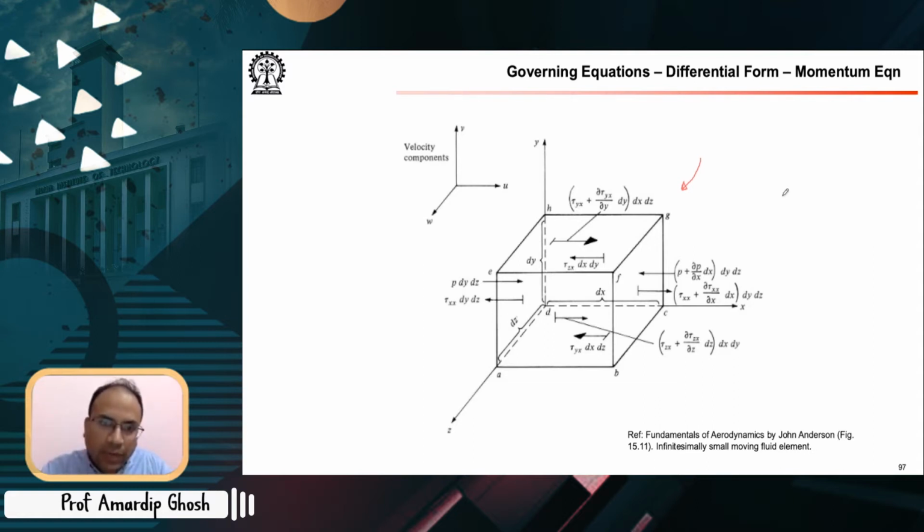One of the many answers is, as you have seen, if you non-dimensionalize them, you get those physical parameters, the non-dimensional parameters like Reynolds number, Mach number, Prandtl number, which tell you of the dynamic similarity between problems. Remember, these things are known as similarity parameters.